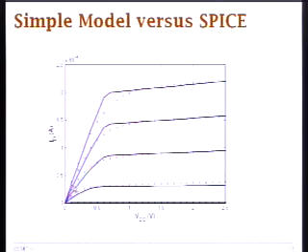As we see, you have pretty good agreement of the model in 2 regions of interest, in saturation mode and also in linear mode. Over here in this transition, you don't really care much. And even if you end up in this region and still use your model, it's still a good first estimate when you design your circuit.